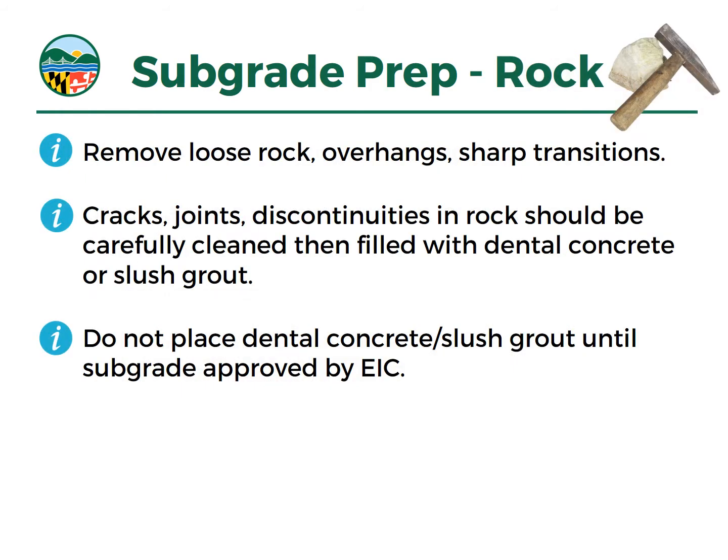All right, rock subgrades are a little more tricky sometimes. It really depends on the condition of that rock. If you're in the Piedmont area, you might be in a highly weathered rock, saprolitic condition. And in that case, are you going to treat that subgrade as rock or soil? That's where some geotechnical testing, maybe test pits or soil borings ahead of time, will help the engineer decide what the appropriate methodology is. And then that methodology should be incorporated in some kind of project specifications or at least notes on the plans.